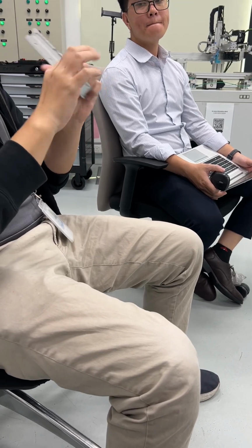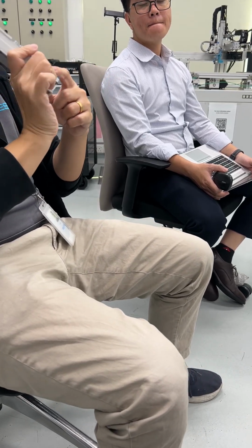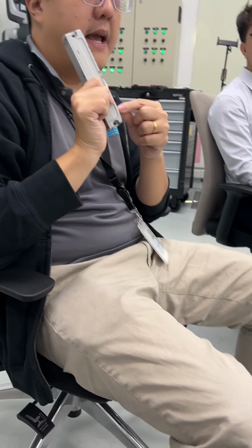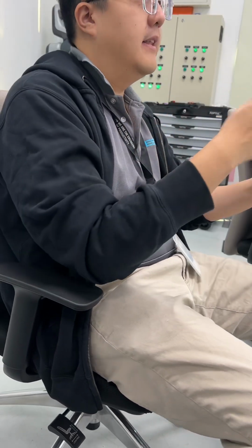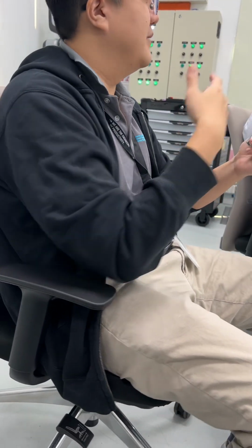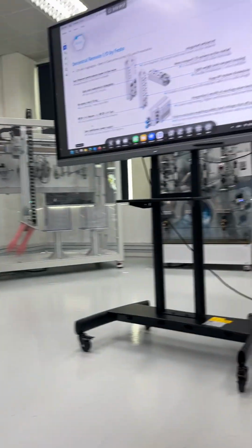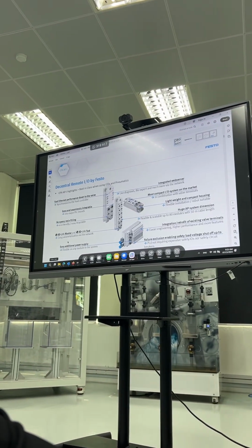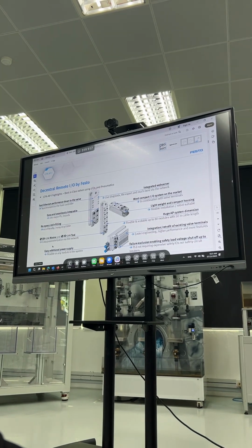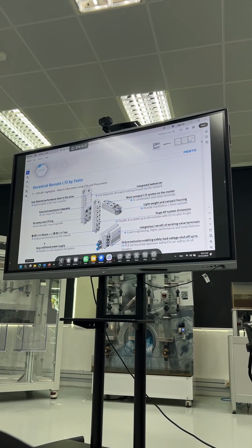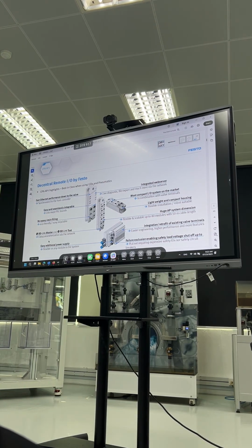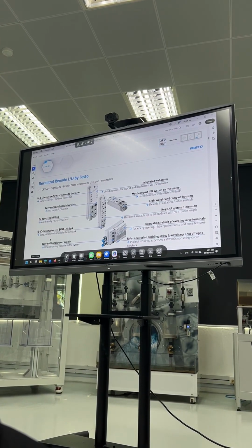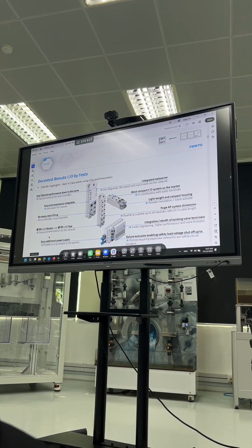If you check the module, each module has a power supply for the sensors and the load supply, up to 4 amp. But the thing is, just now we mentioned you can have up to 79 modules. If you have 79 digital output modules and you connect them all in a straight series, you might not have enough power supply for all 79 digital output modules, because as mentioned, they have an internal fuse inside and the maximum is 4 amp.